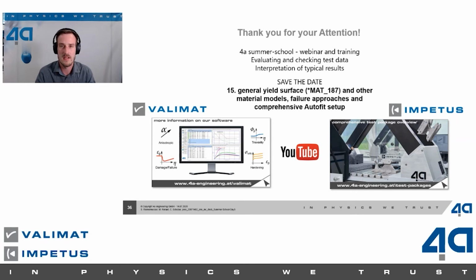That means we are just measuring the strain in a plane area, in two directions, the X and Y axis. So we can calculate the Poisson ratio from this strain measurement, and with this Poisson ratio, we can derive the volumetric strain.